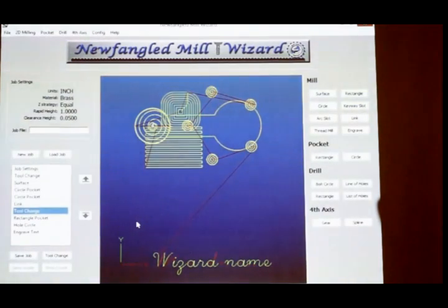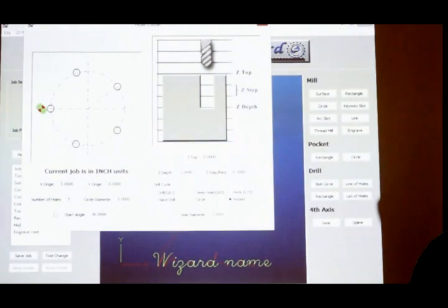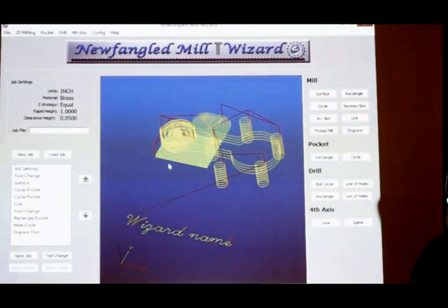Is this using the same post processors you selected with Mach? No, this doesn't have a post. It just generates native G-code, in the simplest form. Again, keep it simple, okay? I don't use cutter comp and offsets and all that kind of junk. So it's going to use pretty simple G0, 1, 2, and 3, and for the drills, the G81, 83.